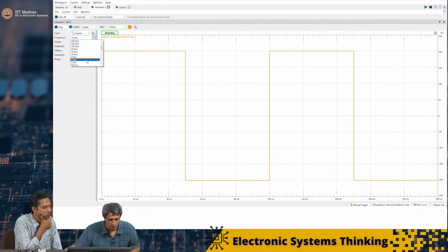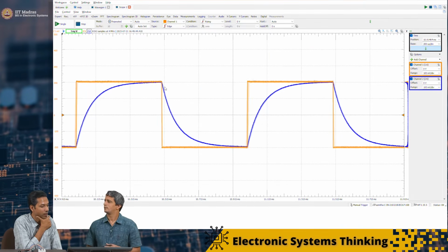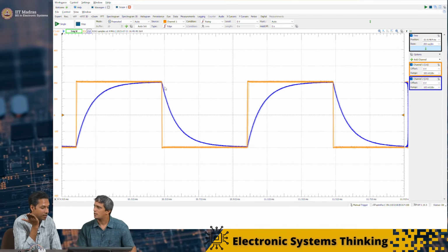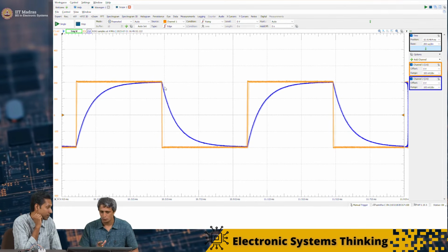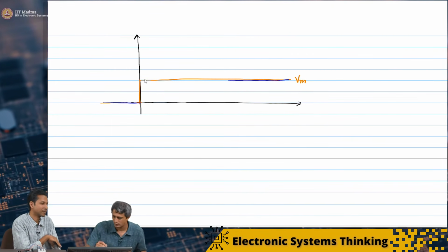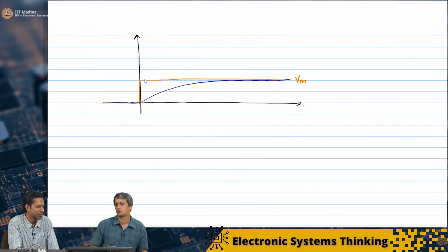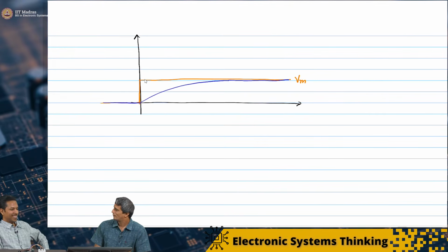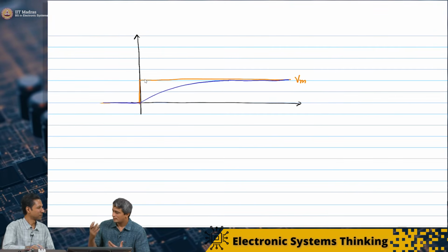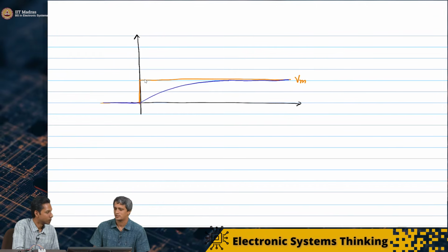Okay, so I gave maybe 1 kilohertz, let me give it. So this is the thing: it starts at 0, it's getting asymptotically to the final value, 200 millivolt that we have given, but in between it's a smooth continuous curve. It's an exponential curve like this. So the mathematics helps? Absolutely, the theory indeed validates the practical observation that we make.